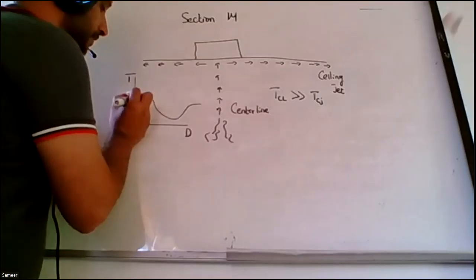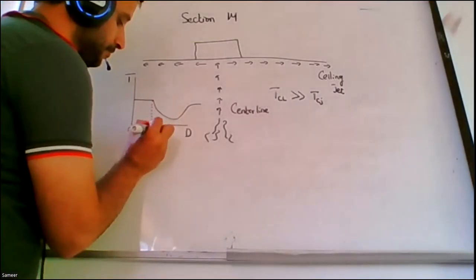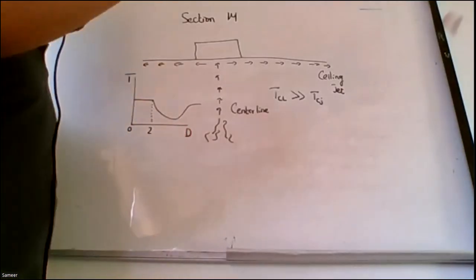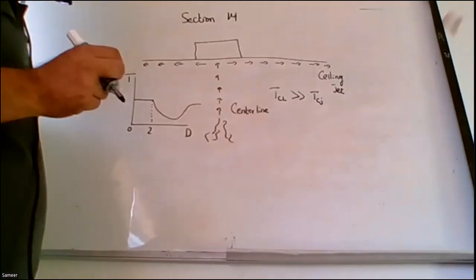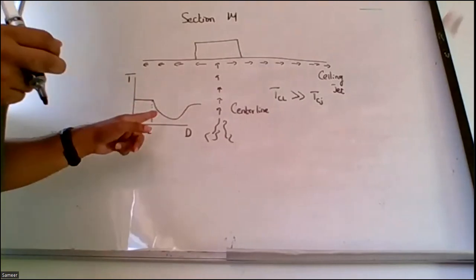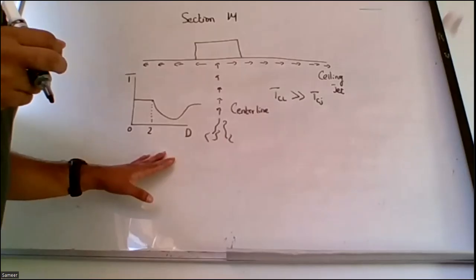This consistency is from 0 to 2 meters of distance. From the third to the fourth meter, it tends to distribute effectively. This is the area of effectiveness for the heat detector, up to 2 meters.